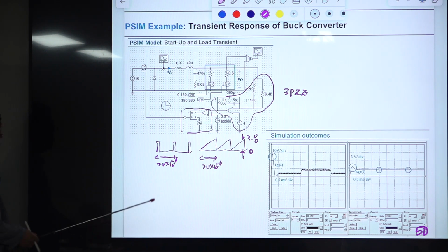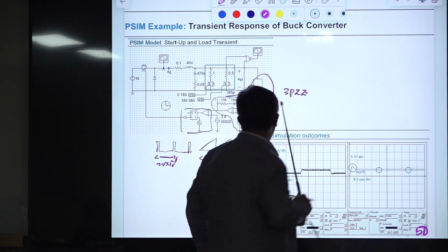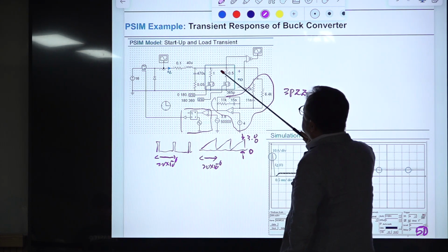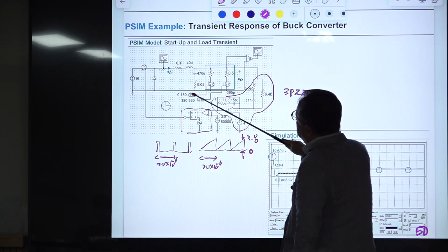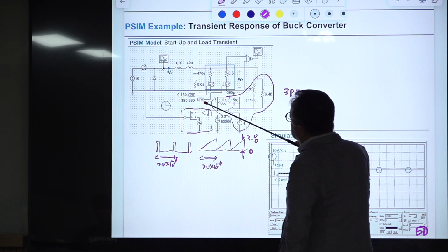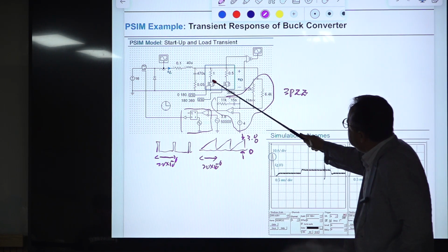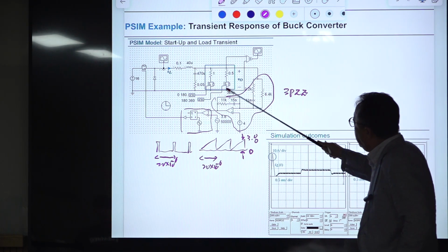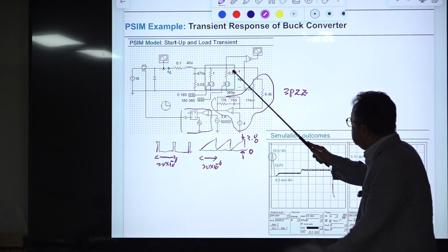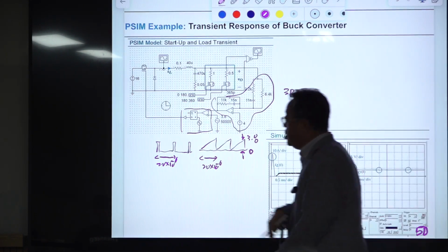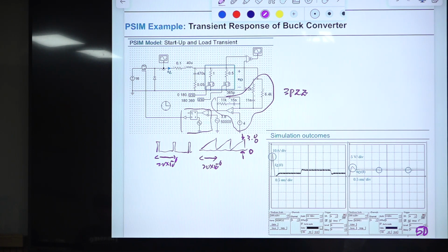All right. This is the waveform of this, and this part is the step load transition, and this drive signal is functioning in a complementary manner. So for half the cycle, this is turned on and this is turned off, and in the remaining half cycle, this is turned on and this is turned off. So you are switching 1 ohm and 0.5 ohm. So R is 1 ohm and 0.5 ohm. Okay, they are alternating, and this is a transient response.